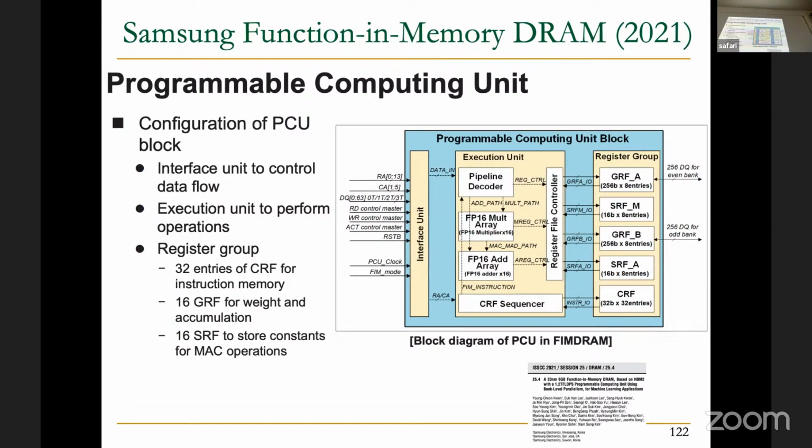So they are key, and we also perform this multiplication and addition in parallel because these arrays are in reality SIMD units that can operate on 16 operands at the same time. Observe as well that these ones don't have any issue with floating point. In fact, they are native 16-bit floating point. They can natively handle 16-bit floating point values.